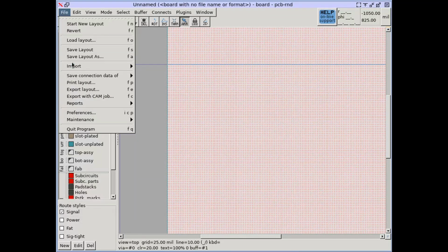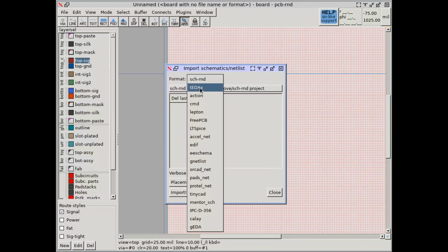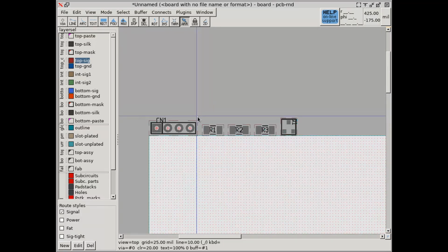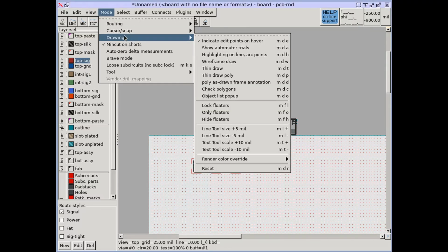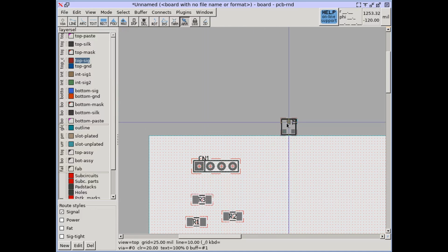The majority of the boards are drawn with a schematic. In this setup, typically all footprints are specified on the schematic, and the schematics or netlist import step will automatically place the subcircuits from the library. This is the same process, using the same library path configuration and parametric footprint syntax as if the user manually selected them in the library window.